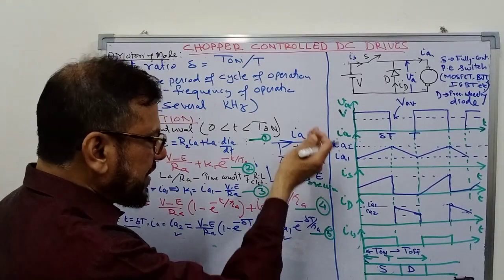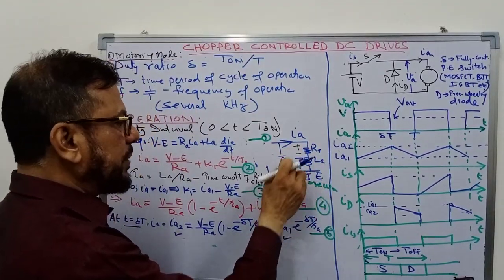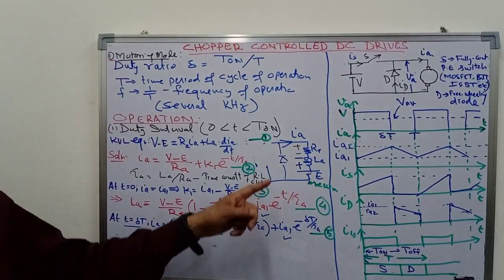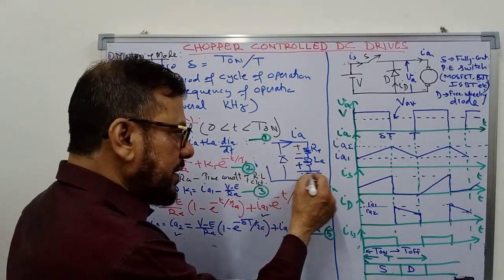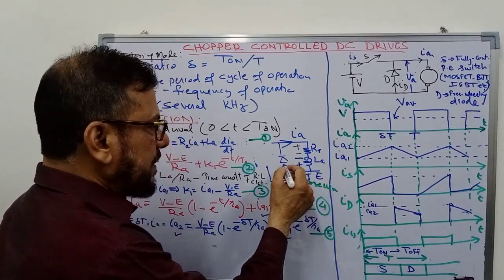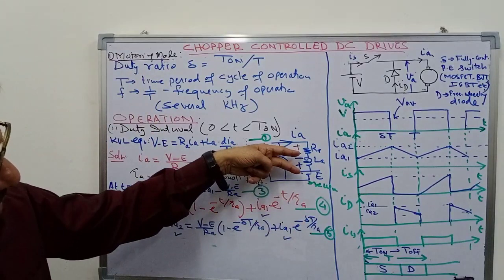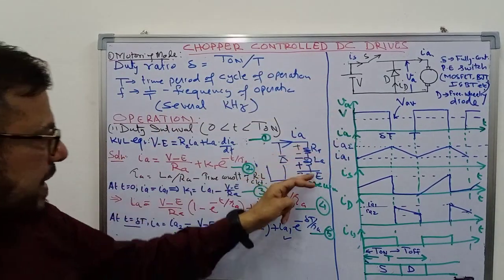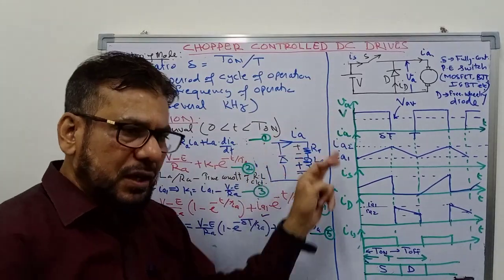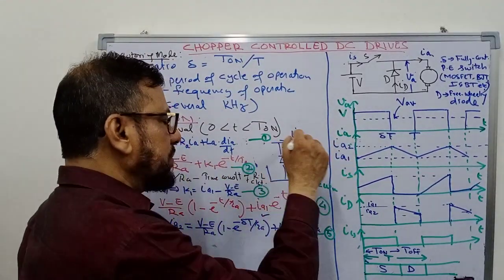So this voltage will rise and it will become so high that it will turn the diode on. Even though this back EMF will try to reverse bias the diode D, because of this inductor voltage, it will overcome this back EMF and will put the diode in the forward bias state, and current will start flowing through this diode.